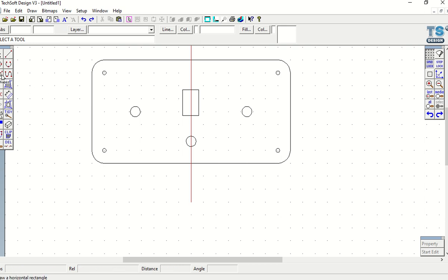Well, let us get off of gridlock, and we need to be 3 millimeters bigger. Right, so that is exactly on that point, and I'm going to pull out. I say it's exactly. I'm not on anything, right? We're going to go to step lock. That's better. Right, that's exactly on that point. And I'm going to come out 3 mil. How do I know it's 3 mil? Well, it says down the bottom, doesn't it?